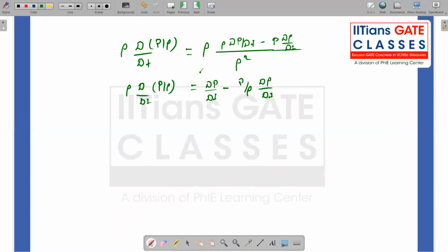Now I have the continuity equation. This gives me d rho/dt plus density field times divergence of velocity equal to 0. This is the continuity equation of the other form we discussed. So now I have d rho/dt in this equation, and I can substitute this d rho/dt to here.